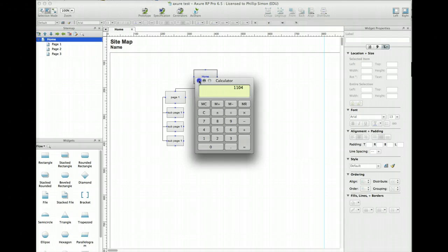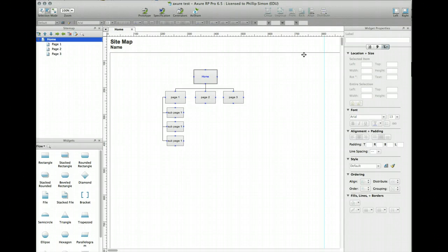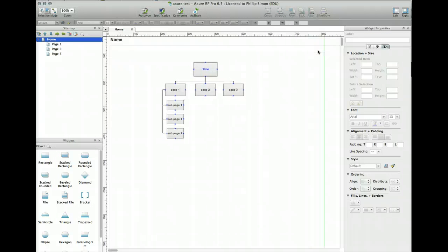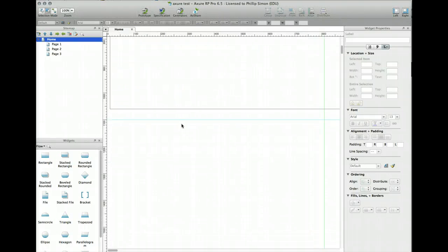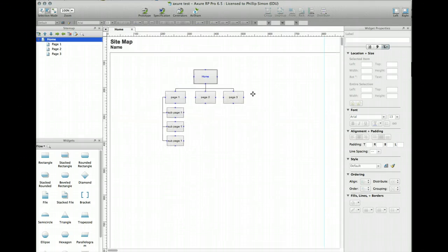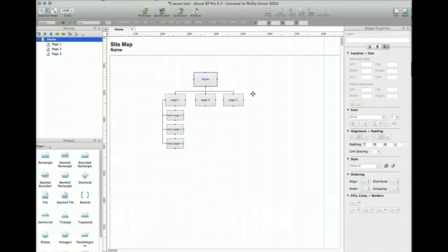So rounding that off, I drew two guides here. This blue line, and this one I set at 810. This bottom one here I set at 1100, and those guides basically determine my safe area for an 8.5 by 11 page.